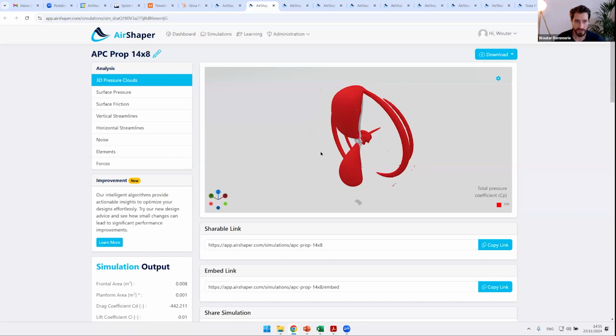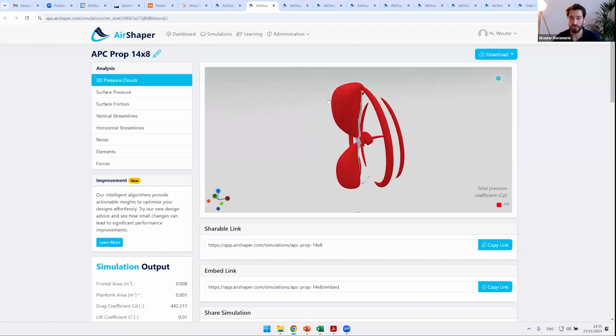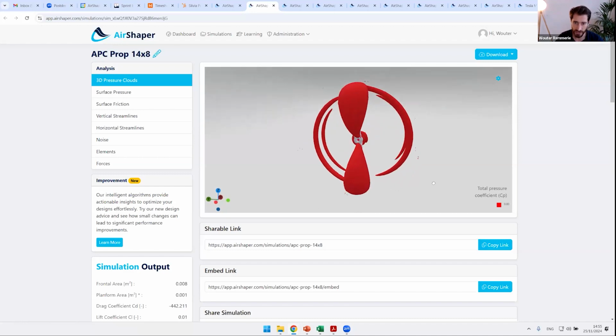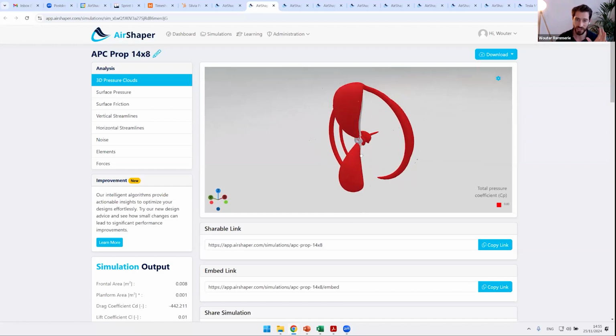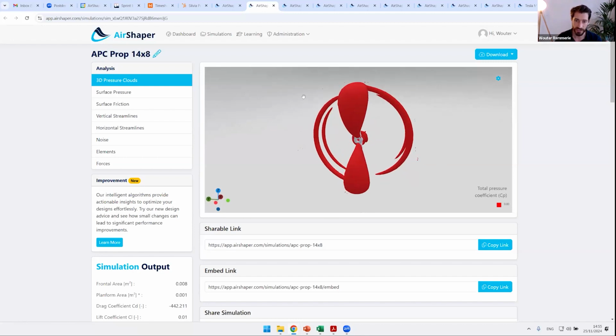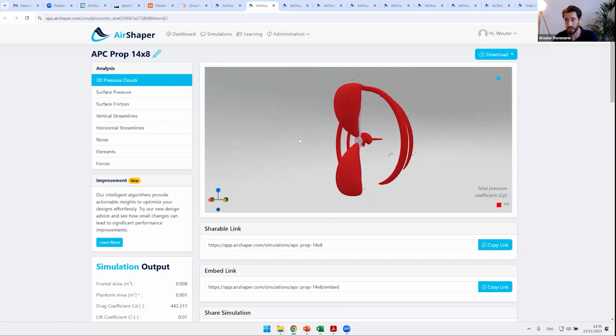Just to run you through some examples, you can, of course, apply aerodynamics to rotating geometries. In this case, it's a matter of automating what we call an MRF zone, which is a moving reference frame around your propeller. If you don't want a sliding mesh, which is also possible but more complex and time consuming, and you still want a steady state simulation with your propeller in one single place, you can build a cylindrical domain, for example, around your propeller, or at least a revolved object. Otherwise, it doesn't work properly.